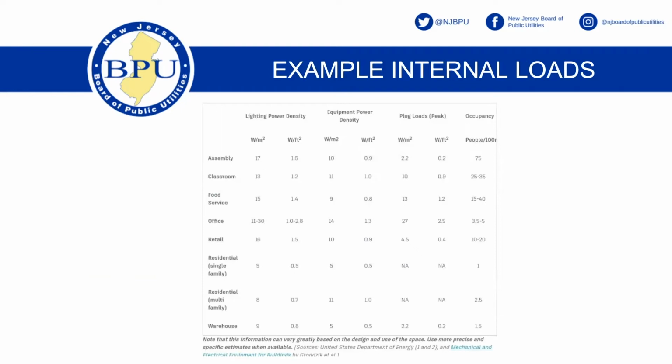So in classroom, food, office. Okay, lighting, plug loads, here we are. You see the plug loads, the second to the last column on the right? Those are given, and actually look at just the second column from the right-hand side. That's in watts per square foot. Most of us don't think about watts per cubic meter, but watts per square foot.